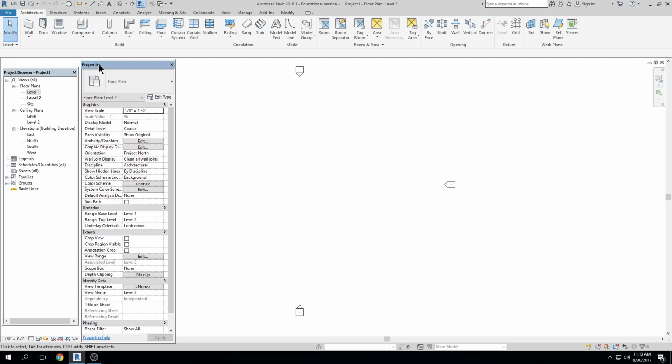Okay. All right, I want to remind you that we have some visual settings down here. We have this kind of visual tool palette down here where we have scale. This is where you're going to change scale. And I just want to remind you that all of these objects down here are view specific, meaning when I change these, it will change it in the view that I have currently viewed on my screen. Not the one stacked behind that view, but that current view on my screen. All right, it won't change it universally.